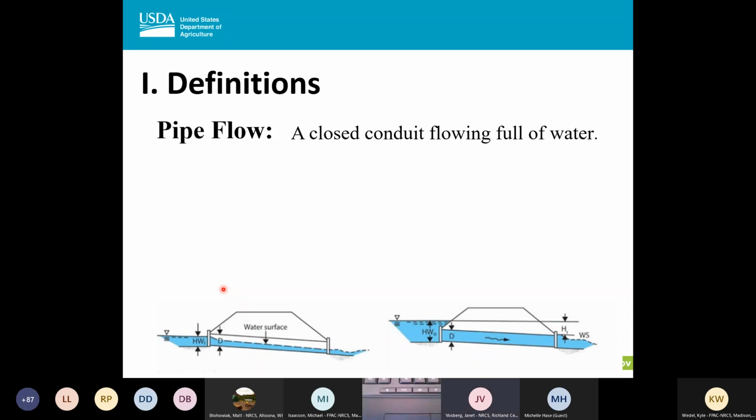I presume you'll talk about that later when you talk about drop structures. Yeah, a little bit. In general, for the drop structures, you have to check weir flow, the high orifice, which is the riser dimensions, and then the low orifice, which is the outlet pipe. And oftentimes it's the low orifice or the outlet pipe that ends up controlling, but we can talk about that later when you get to drop structures.